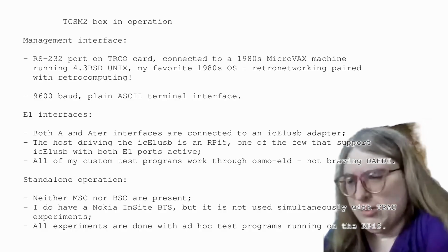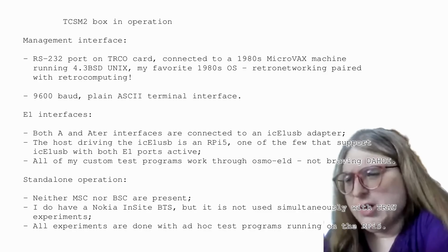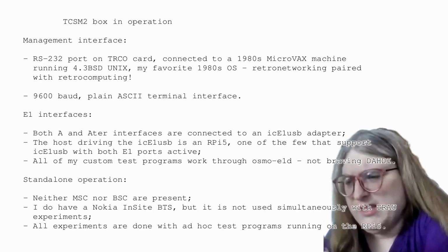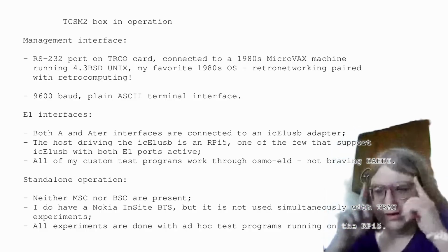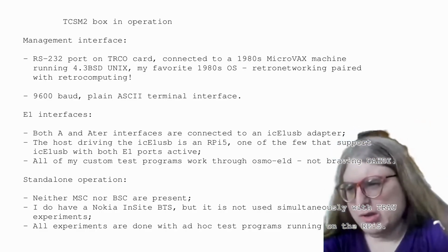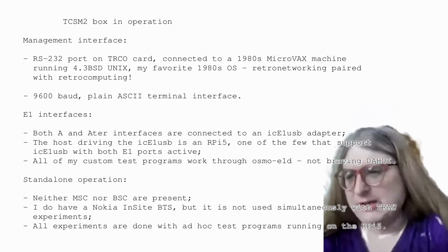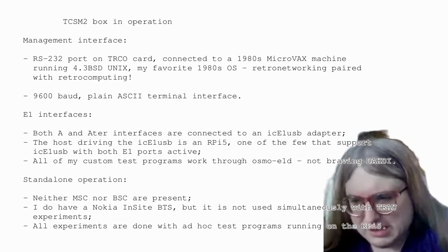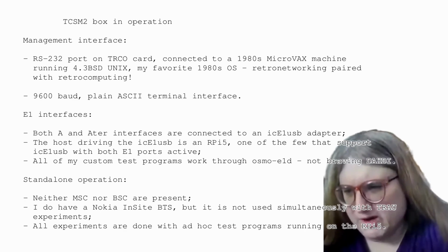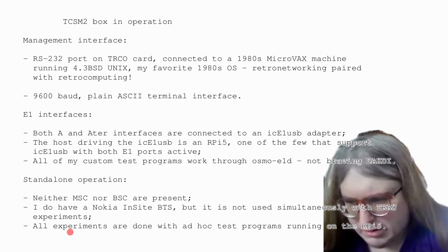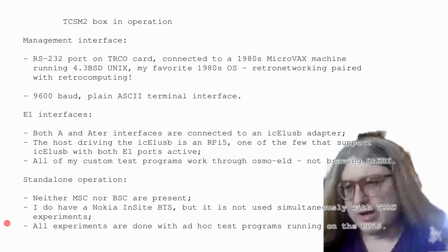They link with libosmocore, libosmo-trau, libosmo-sdn, but I'm not going through the libosmo-abis E1 input layer. That one seemed a little bit of a learning curve. Haven't really got into it. So I also link with the osmo-e1d client library, and that's how I connect to the individual timeslots. So I'm sure it can be modified to work through the libosmo-abis E1 input layer, just more learning curve. But so that's how I operate this thing.